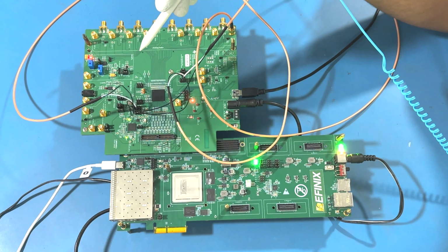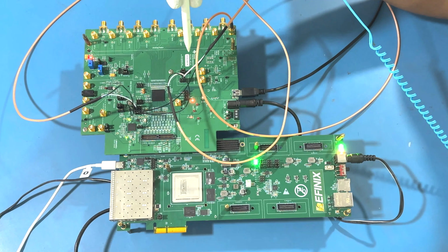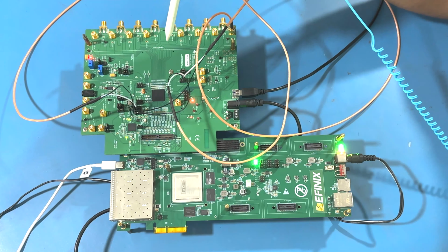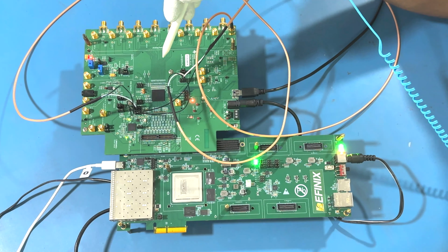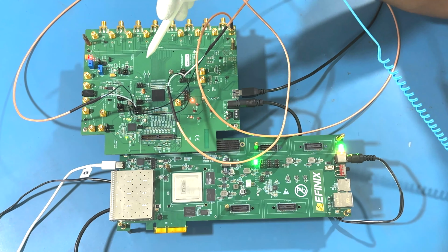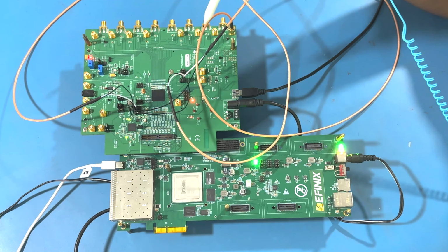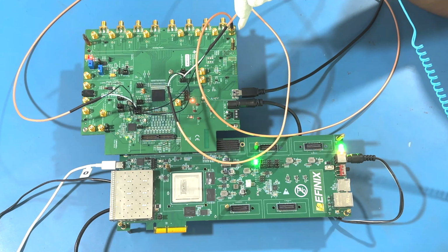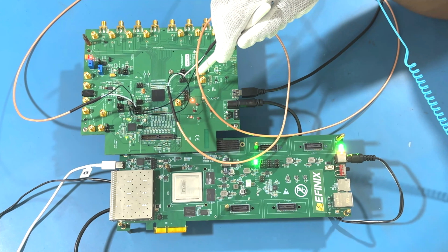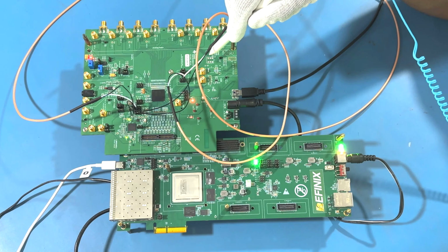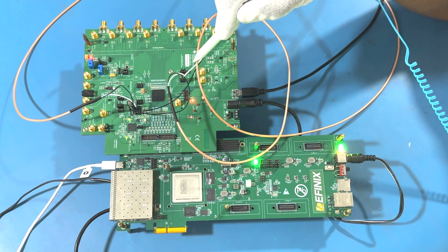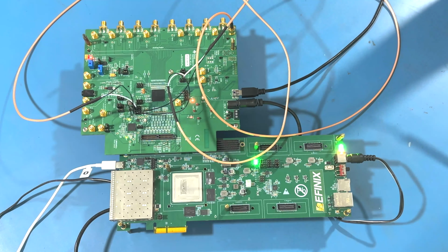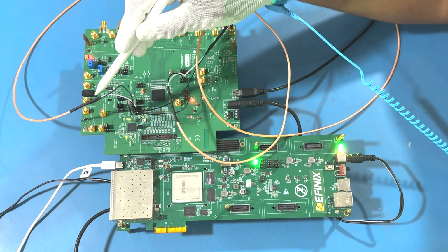So in the setup, we have mainly 3 cables. The first 2 cables are for the data generation. One of the cables is used for the ADC input. We are generating 2.44 MHz of synchronized data through the LMK itself, and we are sending that to ADC input channel 0. Along with that, we have one more cable which is generating a 2.44 MHz output, also generated by the LMK in a synchronized way, and that is being mapped on the oscilloscope as a reference to check the deterministic latency. Along with that, we have one more cable.